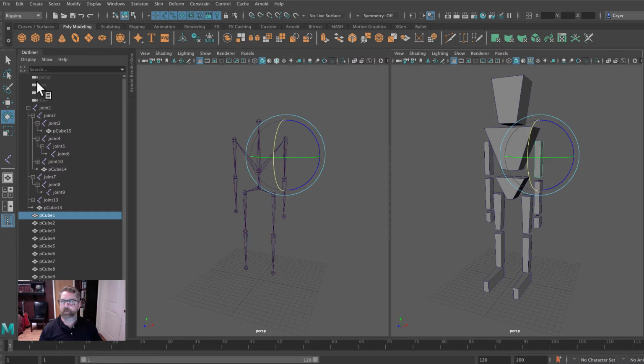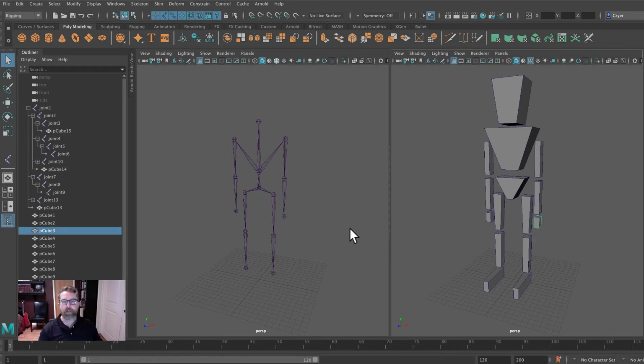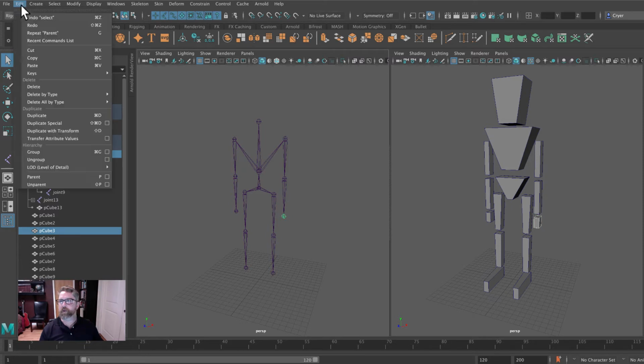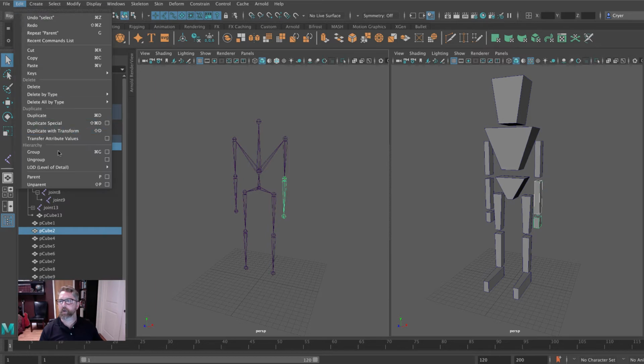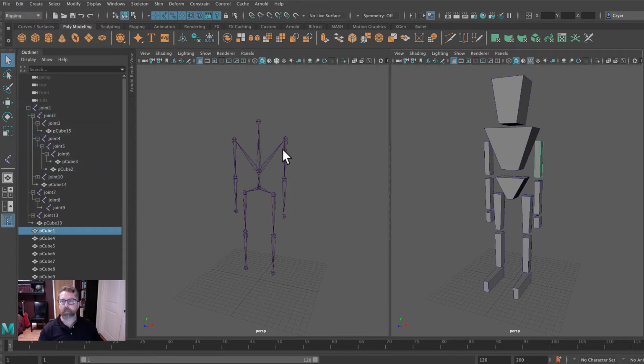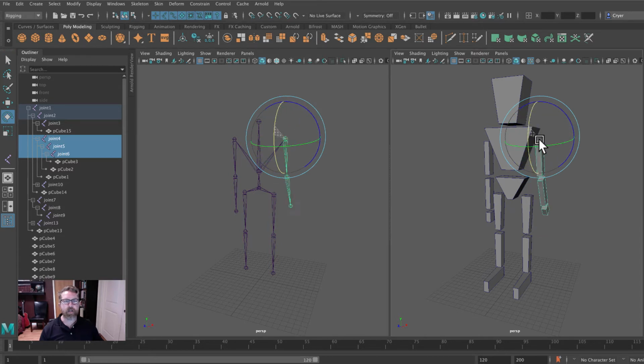All right, we'll do our arms. We'll grab this shoulder, and let me start at the bottom just because that visually is a little bit more difficult. So pick the hand, shift select the wrist joint, we'll come to edit parent. I'm just going to breeze through this. You probably want to check at each one. I'll check the whole arm. I'm confident that this is correct. And if we grab all 3 joints, so we've got joint 6, 5, and 4, we can rotate and you can see the arm working, similar to our robot arm from a few lessons back.